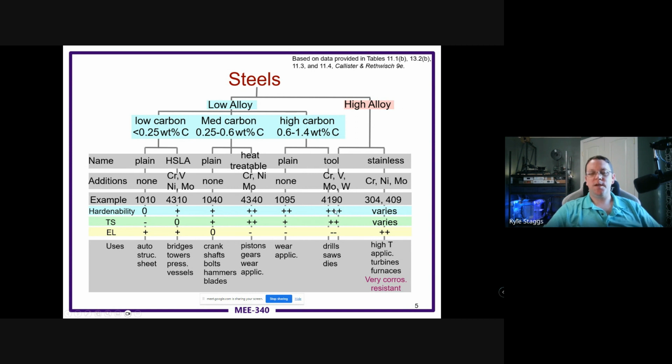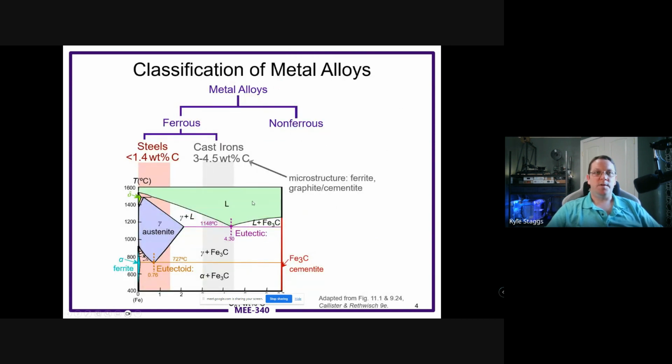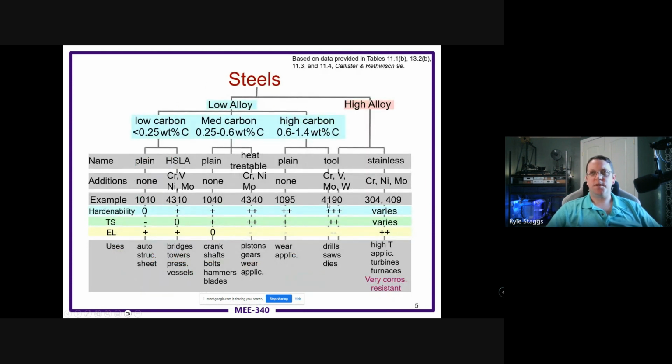The reason there being, when you're up above the 1.4, you're transitioning through a lot of this austenite region. So you can change the ratio of carbide, depending on how you heat it, how far you heat it, and all of those things. Typically, we don't go all the way to liquid. There's a bunch of reasons why. And locally, some of the crystals will rearrange. You can have some local shifts in that phase diagram. So we'll talk some more about that a little bit later.